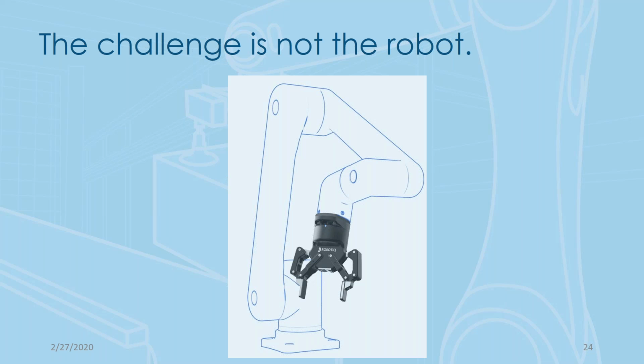It's crucial and vital. There are a lot of different alternatives for solving those types of problems. There's quick change end effectors that the robot can change out itself as it's working, depending on what the application is. There's 2 and 3-up end effectors where, depending on which direction the end effector is pointed, it'll give you different capabilities. But that is something to consider, as we've yet to really simulate the versatility of the human hand and the ability of humans to sense what they're holding and how much.